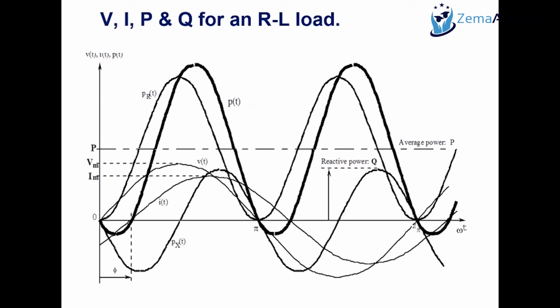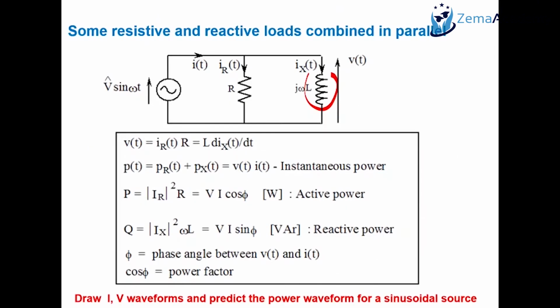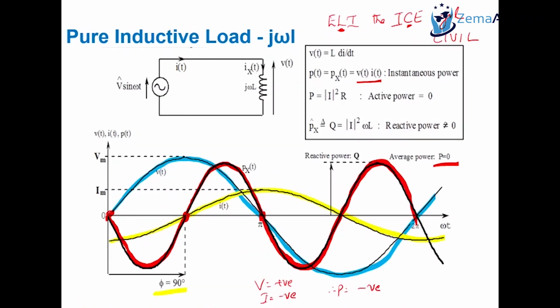Okay? Because in this circuit, there are two components, and we saw how each individual component behaves in a single-phase AC circuit. And therefore, whenever you talk about I squared R as an indication of how much power is being dissipated and the current that needs to be accommodated in a cable, you should also keep in view the reactive power that flows between the source and the load, which also needs some space in the cables.